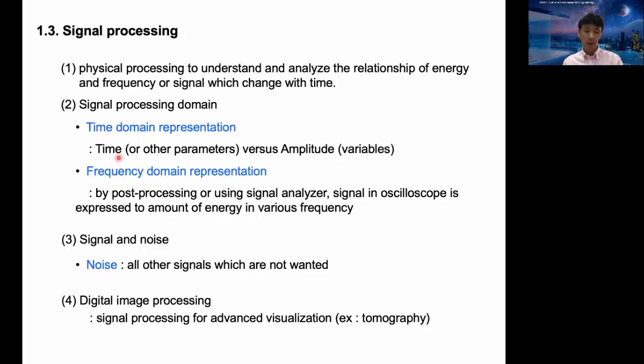The time domain method is when you have a signal that varies with time, you filter or condition the signal in the time domain. The frequency domain method requires the fast Fourier transform, so you convert the time varying signal into the frequency domain, and then do some tricks to get the signal that you want, to remove the noise in general.